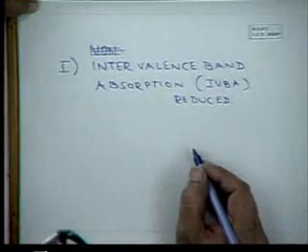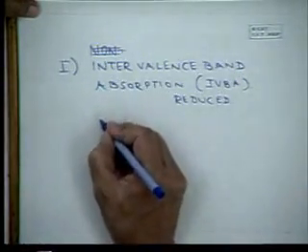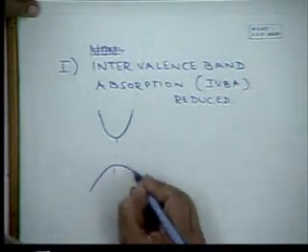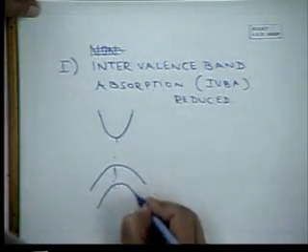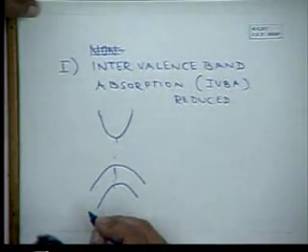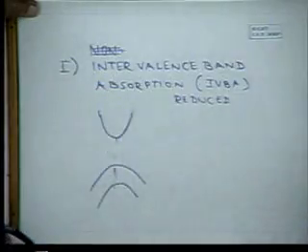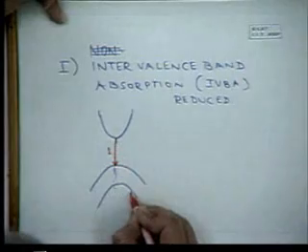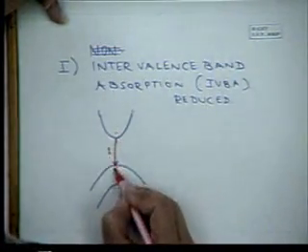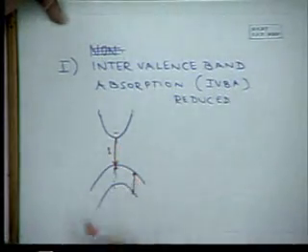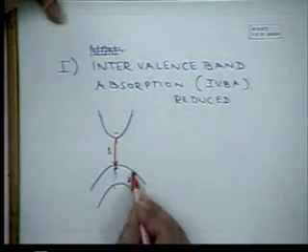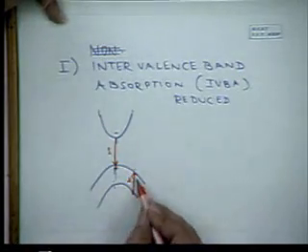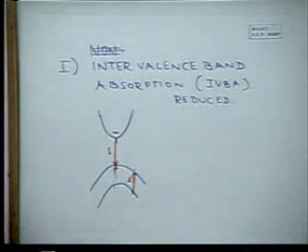What is this phenomenon? If you have a conduction band and here are the two valence bands, this is the split-off band. When light is emitted, this can give rise to self-absorption. This light, due to electron-hole pair recombination here, can be used to excite a hole from a split-off band here. So this means that effectively the radiation efficiency is lowered.